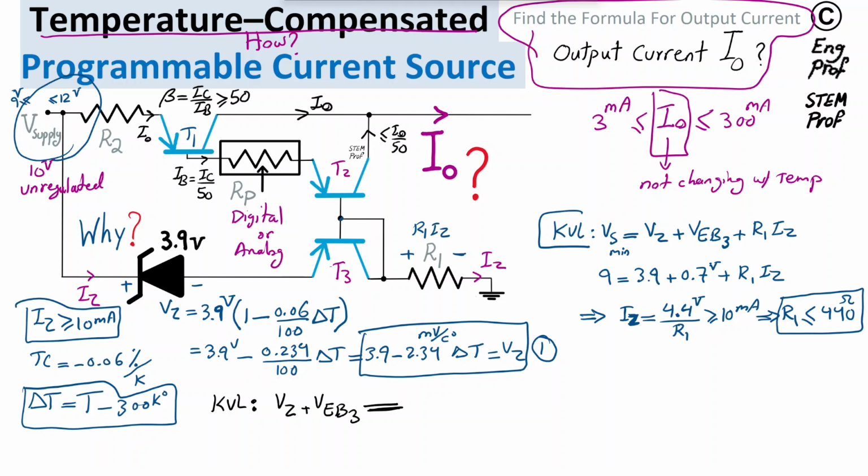Okay, so what do we get now? If we want to be accurate, we can just write beta plus 1 divided by beta, or so beta over beta plus 1. So we can say this one here, effectively in this circuit, is just 1 plus, let's say, 1 over beta times I out for this current, because it's an emitter current.